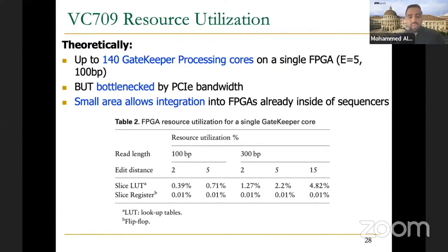So the critical path in FPGA implementation is very important here, so that you can drive a lot of these gates in parallel. Sometimes you cannot apply the VCC or the ground to a large number of gates, and that's specified or controlled by the total critical path or the worst delay in any of the input signals, for example. So you may need to use pipelining techniques to reduce this critical path, for example, or you reduce the number of replications. These are all challenges when you implement a parallelized algorithm in FPGA, or you would like to fully utilize all resources you have in the FPGA.